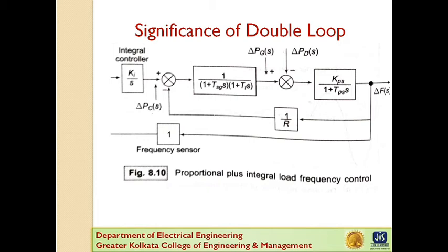The system frequency specifications are rather stringent and therefore so much change in frequency cannot be tolerated. In fact, it is expected that the steady state change in frequency will be zero. While steady state frequency can be brought back to the scheduled value by adjusting the speed changer setting, the system could undergo intolerable dynamic frequency changes with changes in load.